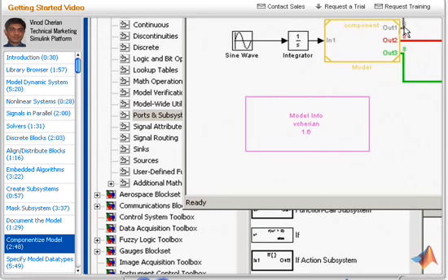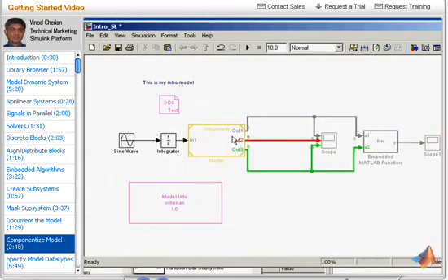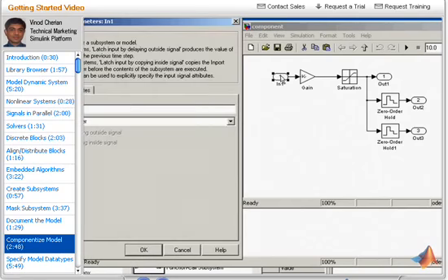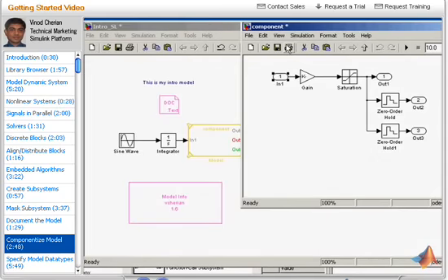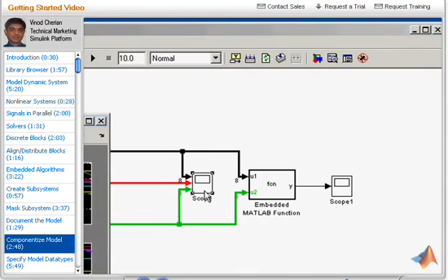As you can see, it aligns from a continuous time to sample time, and let's see why this happened. If you double click on this model, you can see that there are no continuous parts in this model, and everything in this component can be run in discrete time. So what I'm going to do is force it to use a continuous sample time for the default input. I'm going to save this now, and I'm going to simulate this model. Let's look at the outputs, and this is exactly what the original system had as outputs.